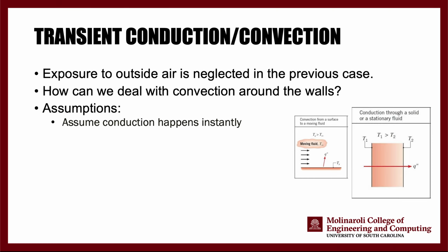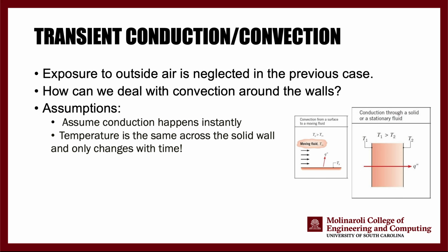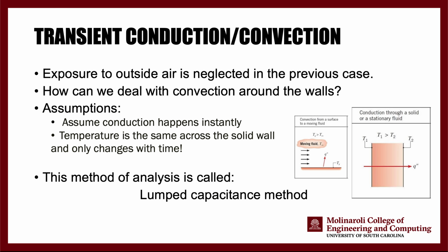That is the assumption we are making, and we are going to test whether this assumption is correct or not after we have done the experiment. Again, essentially the temperature is the same across the solid wall and only changes with time, meaning that the conduction is instant. Conduction happens at a moment.